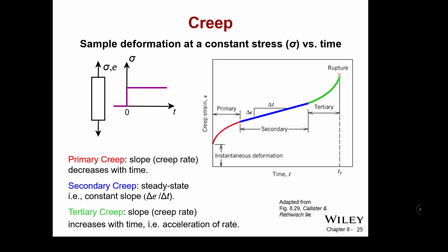So we want to make it harder for it to fail by choosing better materials, by choosing better grades of materials, and by eliminating, wherever reasonably possible, sharp transitions from one geometry to another. The smoother we can make that transition, the longer the longevity of our sample or part is going to be, especially under cyclic loading. And that's very, very important for longevity.